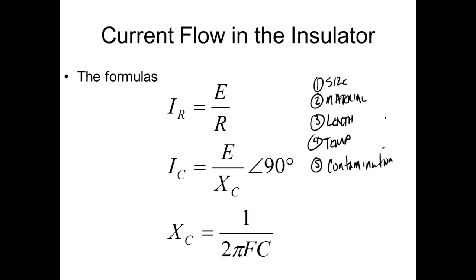So the problem we have with insulators is they're exposed to what? Elements, yeah, and they get dirt on them, they get all this kind of other stuff on them, and that would affect current flow in the insulator too. So you got these cables that spin out a long way. That's why a lot of times we'll protect the insulator with something we call a jacket.